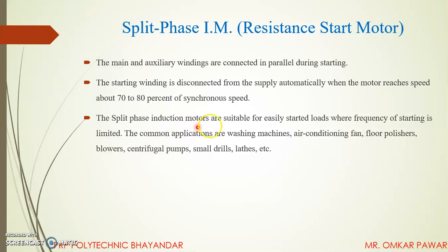Split phase induction motors are suitable for easily started loads where the frequency of starting is limited. The common applications are washing machines, air conditioning fans, floor polishers, blowers, centrifugal pumps, small drills, and lathes.